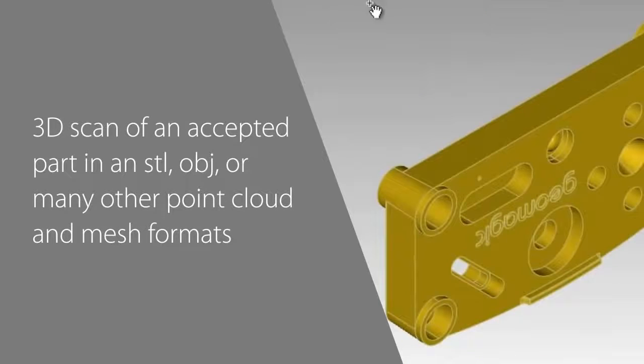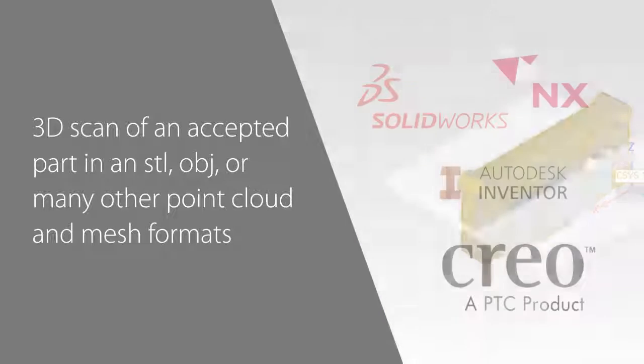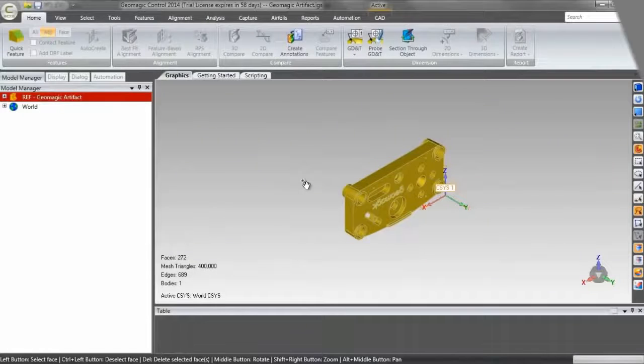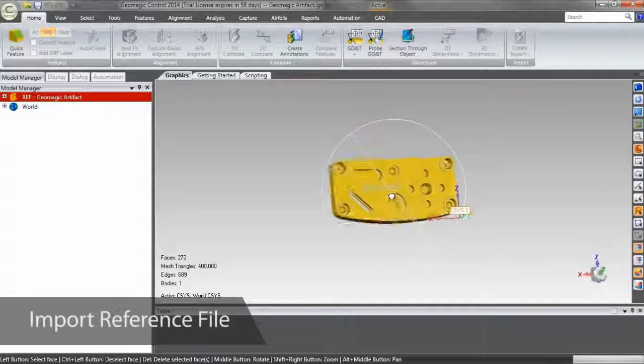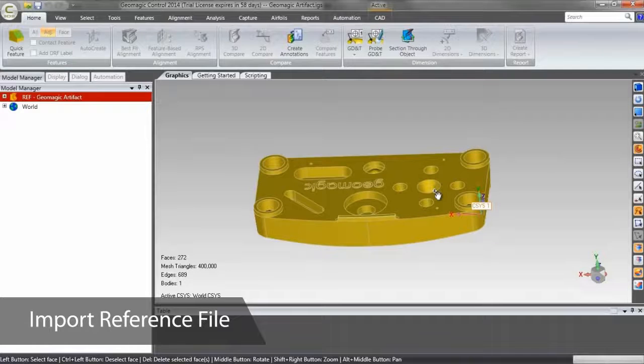This can be a 3D scan of an accepted part in an STL, OBJ, or many other point cloud and mesh formats, or a body created in a program like SOLIDWORKS, CATIA, Creo, ProE, or Inventor. Control will open up files from those programs natively, or generic CAD formats like IGES and STEP, as is the case with the reference file here. Because this is a CAD body, Control assumes it's the reference object all scans will be compared to.